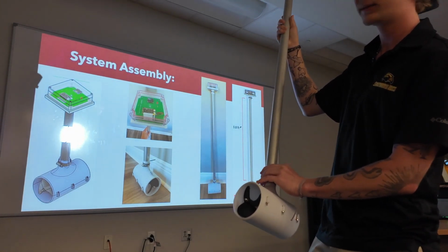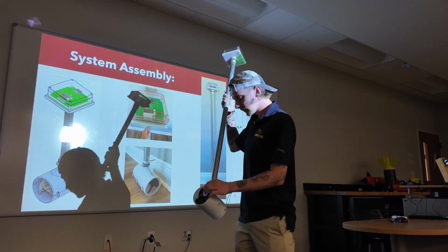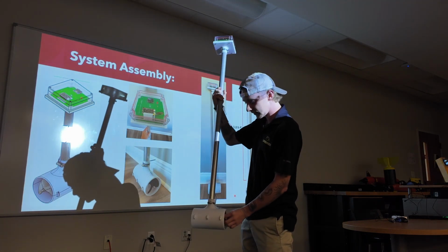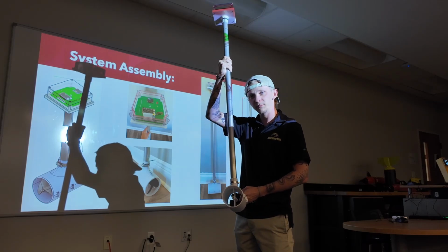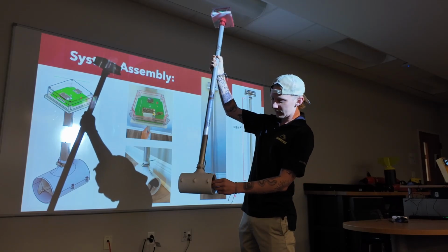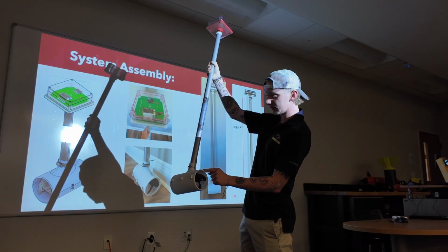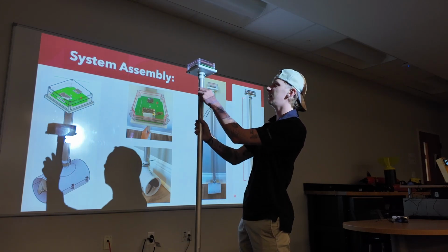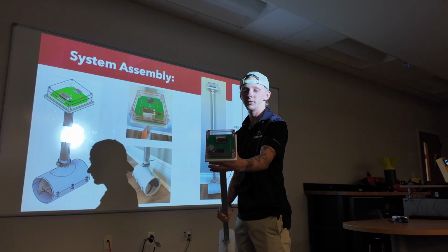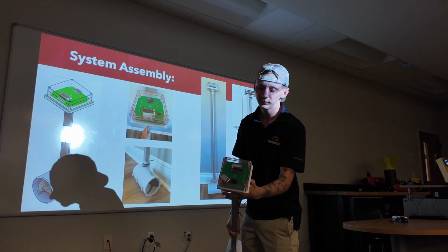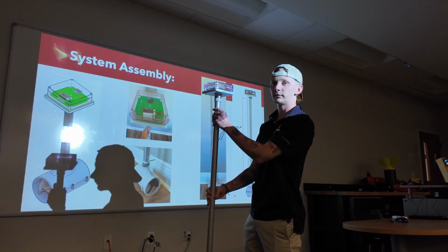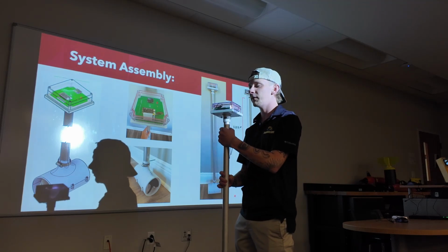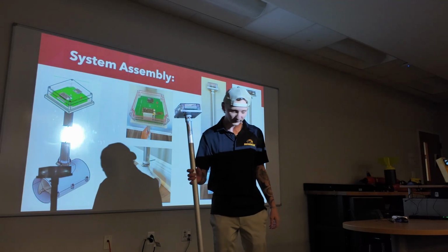Bring it closer. It's probably better if you stay. I don't know if this autofocus is working. But the Hall effect sensor sits on top of here, and if you look, I don't know if you want to zoom in, you see the magnets on the back of the blade. When this spins, that's when it picks up the magnetic pulse, and then it transmits the data all the way up to here, which is the microcontroller. Right. You need to figure out how to secure your battery. Yeah, I left a space because I wasn't sure at the time what size was going in there.